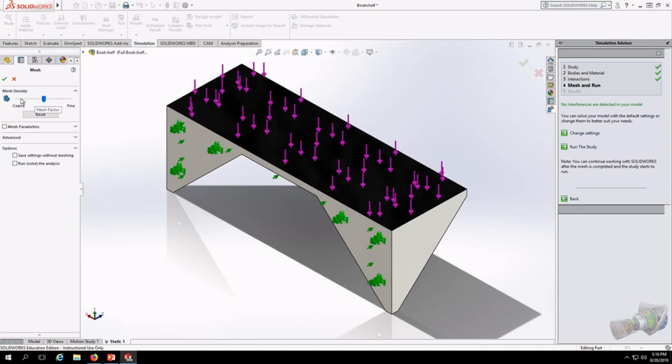At this point, we can set the average density that we're going for, and then hit the checkbox. Oftentimes, the default option is the best one, but there are some occasions where you may want a bit more control. A coarser mesh will run faster, but the results may not be as accurate since you have fewer overall elements. A finer mesh will have more elements, increasing the average accuracy and the computation time. However, this can cause some problems on its own.